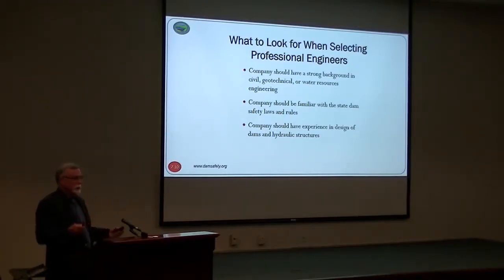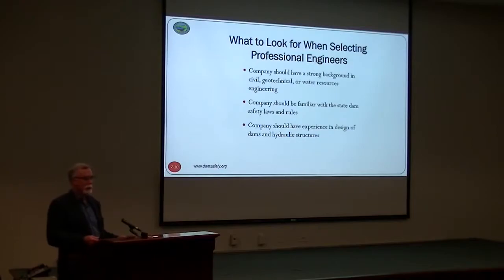As I mentioned, it's a dam, and a dam covers a lot of parts. It covers geotechnical, it's a concrete spillway, you got to have a structural engineer, you got to have a hydrologist, a hydraulic engineer to model your spillway, so there's a lot of components you have to consider. You should be familiar with South Carolina dam safety law. You know, that they've got rules and regulations they have to follow. And design of dams and hydraulic structures. You don't want to hire an engineer that's done roadways or sanitary sewers or water treatment plants. They're good at those disciplines, but dams is an entirely different animal.